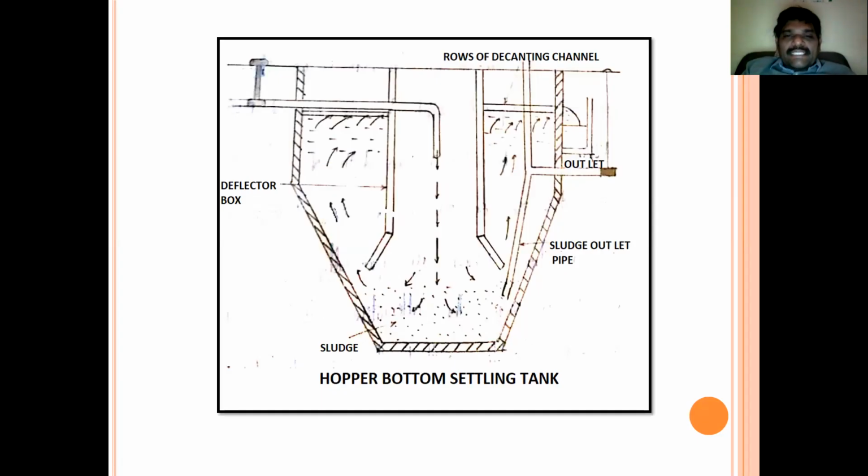While the water is entering in this direction, the waste particles or impurities whose specific gravity is more than one will settle on the bottom as the water changes its direction towards the top end.